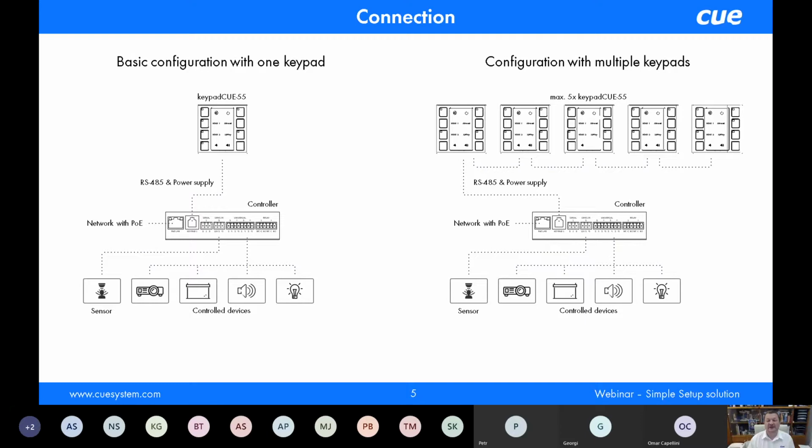So just to give you a brief summary, for RS485 you can have over a kilometer length of the bus, but the powering is more critical, and you will probably see that this voltage drop shortens the maximum length of the bus.